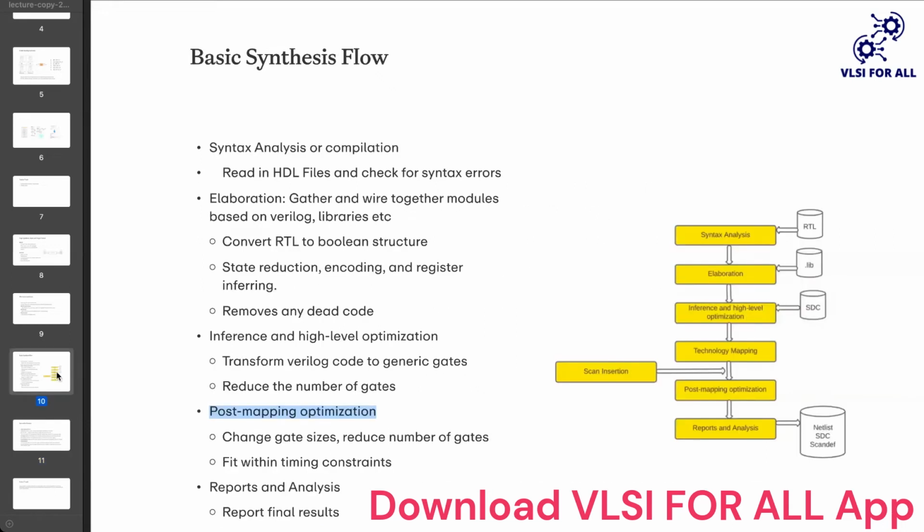Okay, before I go to the next slide, maybe I'll tell you. This logical synthesis previously used to happen with something called a wire load model. It's called a zero wire load model. So you don't have any physical information of wire or anything. Basically, all the wire load and everything is considered as zero delay. Only the gate delays are taken into account.